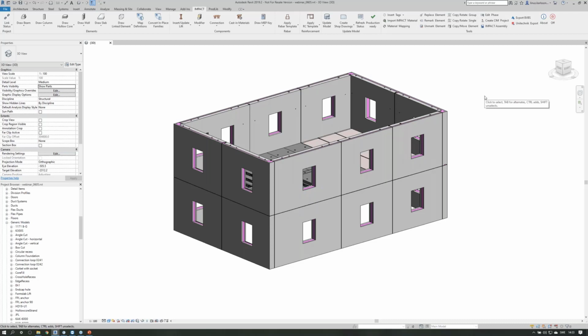First of all, we wanted to present a little bit about the different element types and how, for instance, we add the lifting types or the lifting setups depending on mass and so on. In Revit, there are two general differences between the families. It's either loadable families or system families.